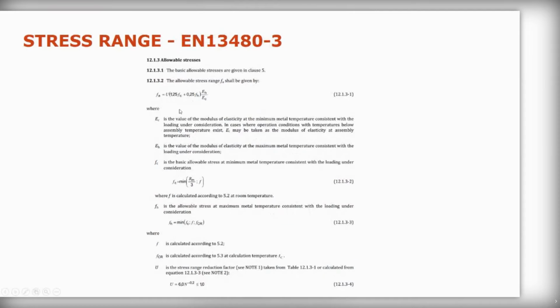Now, in the EN code, again, this is just a snapshot from the code, but it's the same idea: 1.25 times the maximum allowable stress at cold plus 0.25 times the maximum allowable stress at hot temperature. So again, same idea.